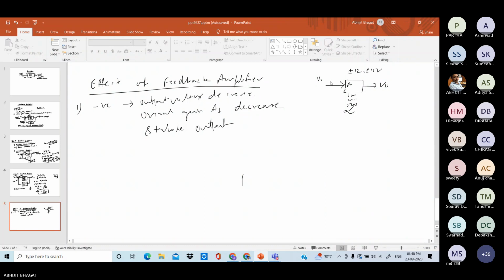Then this is the supply voltage of the amplifier. Now mathematically, suppose you provide one voltage to this input side and your gain of the op amp is 100, so your output is 1 into 100, it will be 100. Okay, mathematically. But practically you are not getting the 100. Whatever the voltage you are getting across the output side, it is less than the supply voltage.